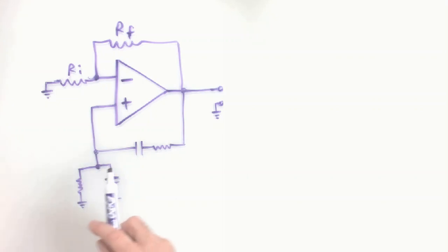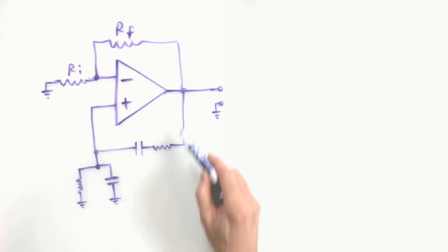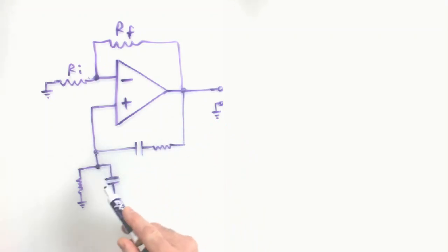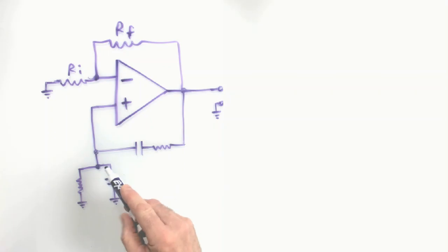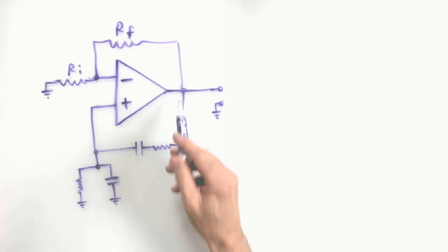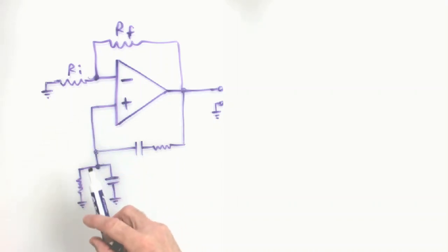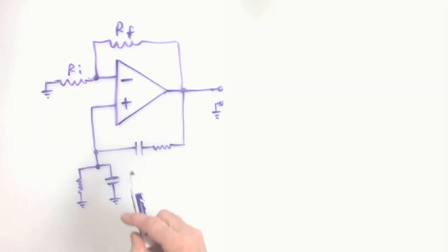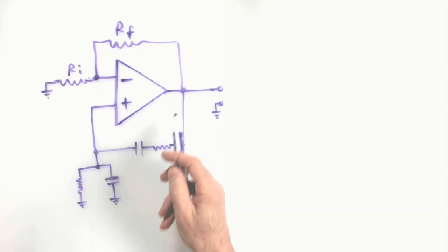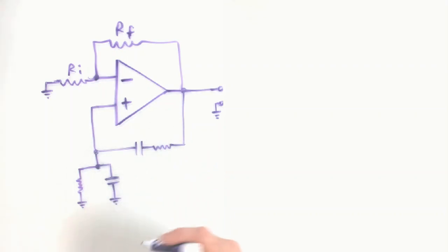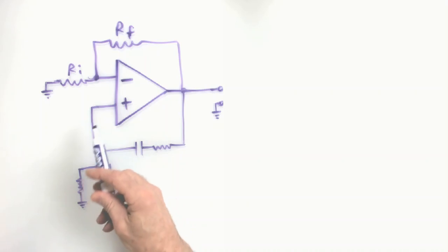So what we're doing here is we're providing a positive feedback path that is best for one frequency and only one frequency. The center frequency of this bandpass network is going to get the easiest time of getting back around, so it will have the highest level. It will also be the one frequency that is in phase, with 0 degrees of phase shift, which is also important. So it'll be the highest amplitude and also completely in phase.